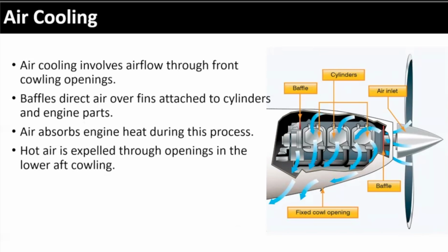All right. We talked about cowling, right? Remember I talked about the cowl covers? Some aircraft have these cowling covers you can open and close that adjust the amount of air flowing over the engine to keep it cool. Okay, cold days, close them up a little bit. Hot days, keep them open. Make sure you get the air circulation. And it's that simple. Air flows through, goes past the engine, out the other side. Constant flow of air to keep it cool.